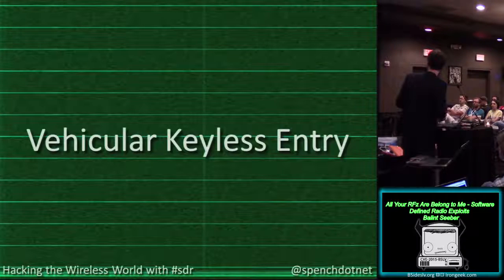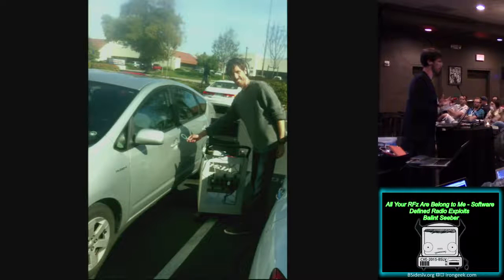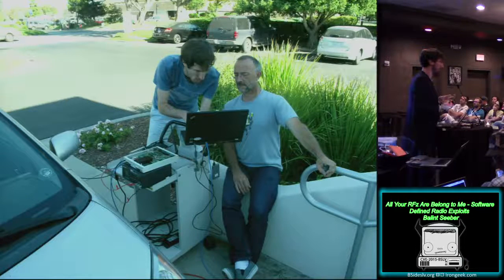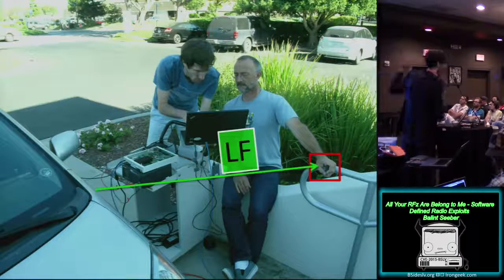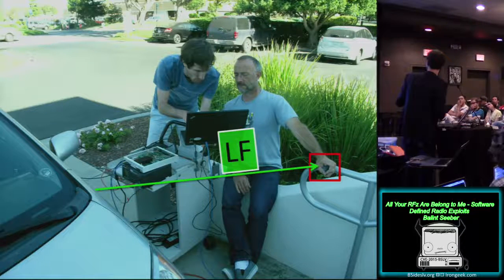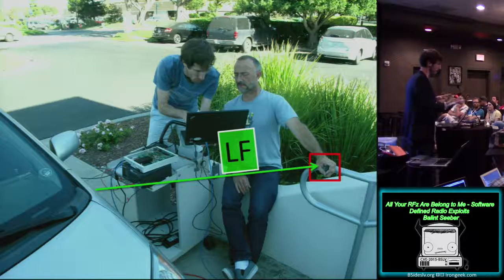So that's that. So vehicular entry, this is something I'd looked at before. You probably all know that in modern cars like the Toyota Prius, you can have the key fob, you walk up to it, there's some sort of transaction that takes place, and magically it unlocks and you can get inside and drive. A colleague had this car, and I wanted to have a look at really how this transaction took place. So here, he has his fob in his hand, and the car is continually broadcasting a broadcast message over low frequency, and the remote control has a 3-axis low-frequency pickup, so that when you get close, it'll detect this message and then initiate a transaction, a challenge response.